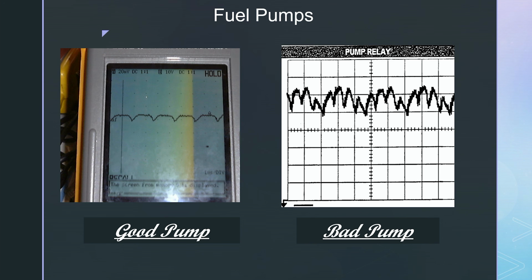So on the left-hand side of the screen is a picture of what a good fuel pump is. Now, this is not a three-phase fuel pump. That's for a future video. On the right-hand side of the screen is what a bad fuel pump waveform would look like. If you ever get a fuel pump that, if the car gets towed into your shop, it doesn't start, or maybe a starter motor or a blower motor or whatever, but if you hit it with a hammer and all of a sudden it starts, well, or the fuel pump starts to turn on or whatever the motor happens to be, one of those little ramps would be going all the way down. That's going to be a short in one of the commutators.